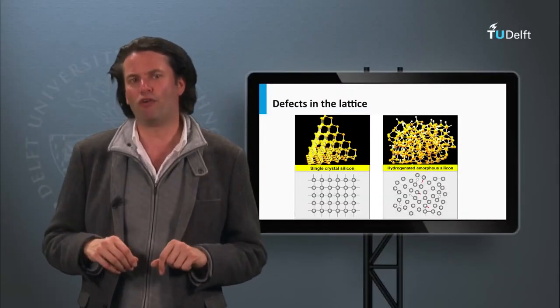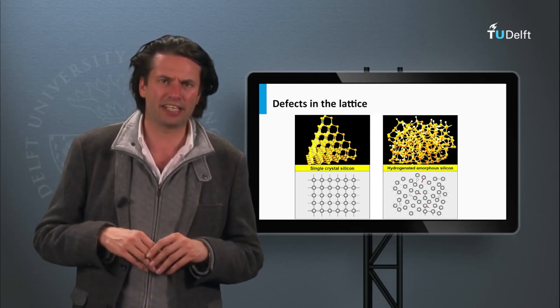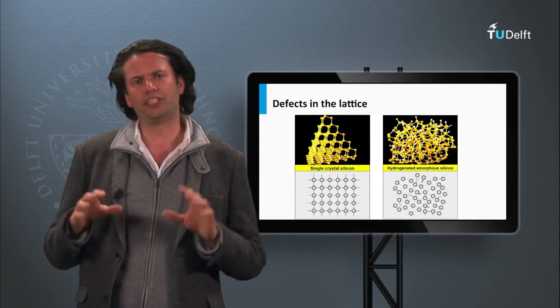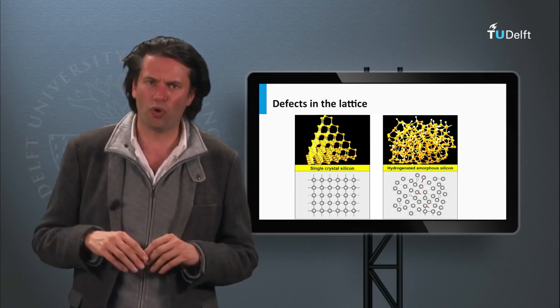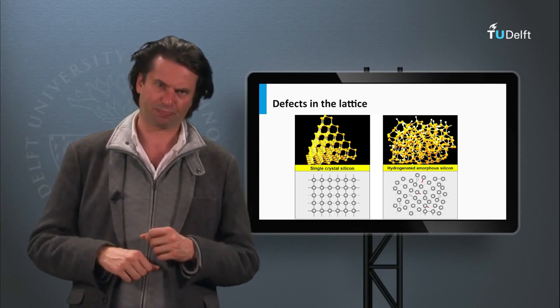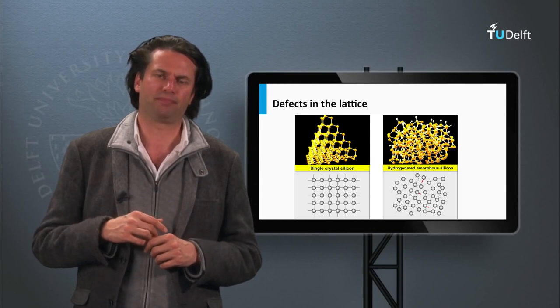The hydrogenated amorphous and nanocrystalline silicon films have a relatively high defect density in reference to crystalline silicon. Due to the disordered structure, not all valence electrons are able to make bonds with the neighboring atoms. The so-called dangling bonds can act as defects.